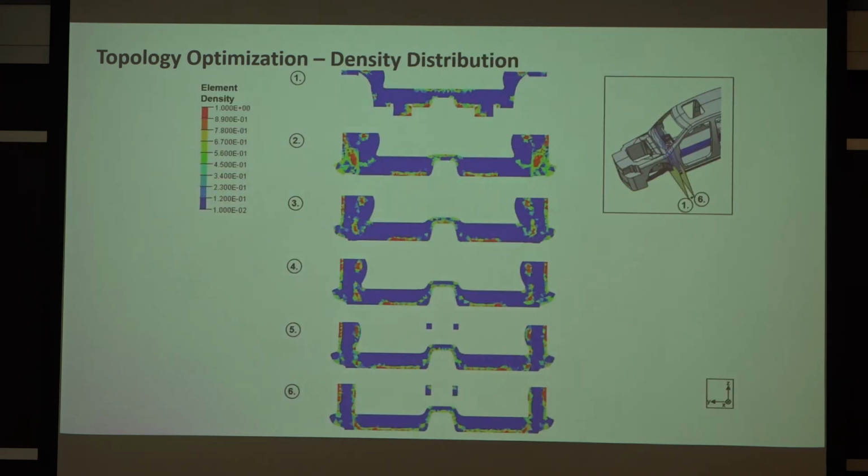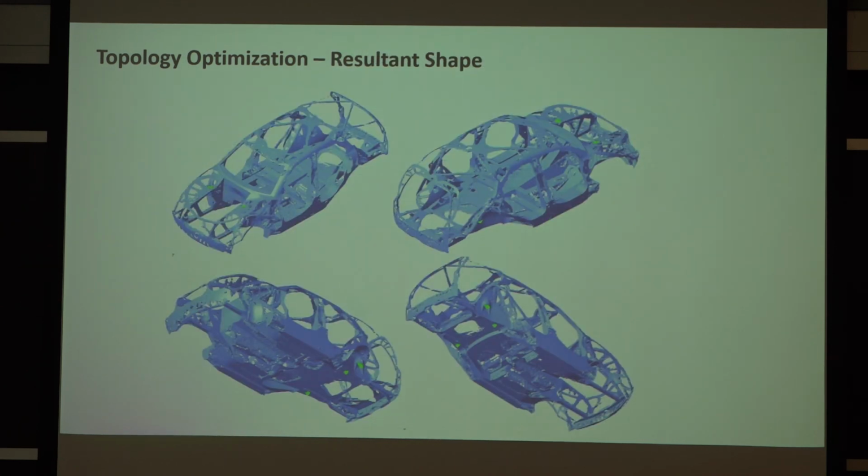We're almost out of time, but I just wanted to show you some of these plots I put together. Some of these topology optimization tools will allow you to look at cross sections of the packaging volume after you've done the optimization, and it'll show you exactly where it's distributed the mass. The areas in red here are the places where the most mass has been distributed. When you look at something like this, it's pretty complicated. It's hard to wrap your head around this. It's even harder to turn this into a sheet metal design. You can imagine what that's like, right?